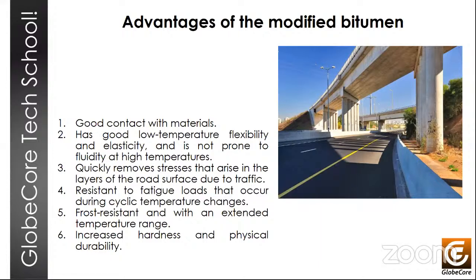So even modern technologies for the production of bitumen do not give much possibilities in this regard, because the improvement of one parameter of the quality of bitumen will inevitably worsen some other parameters. So for example, an increase in the softening point is often accompanied by a deterioration in fracture resistance, or an expansion in the plasticity range reduces the resistance to aging, for example.